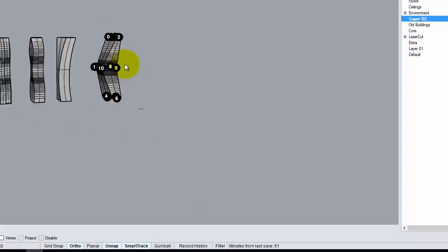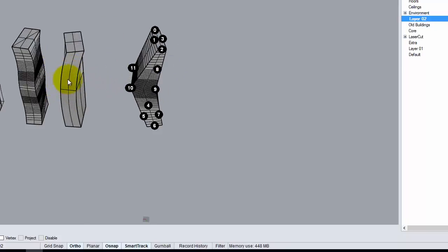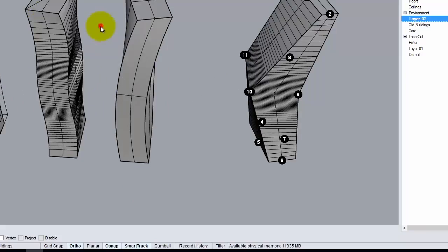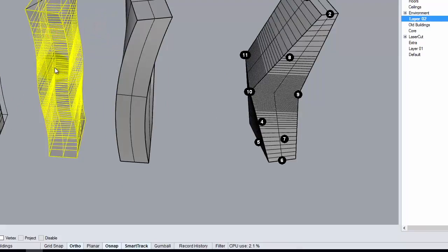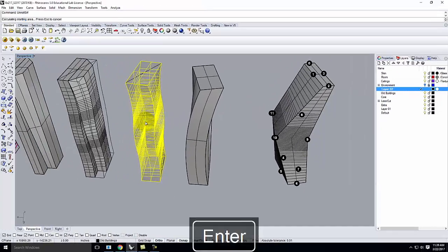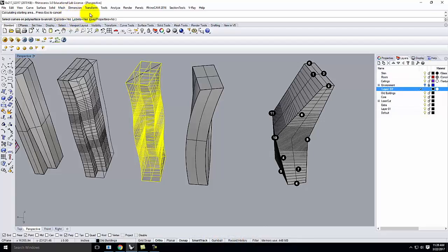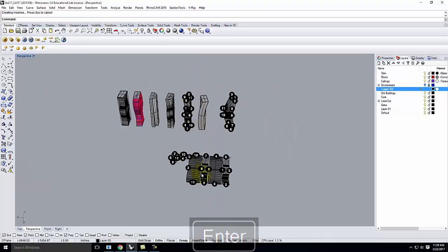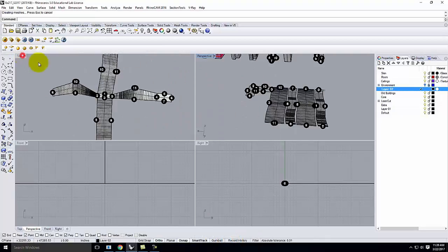So I can do the same thing with a curved surface. And I'm going to skip this one for right now. I'll do something slightly more complicated. I'll do this one. And this is, once again, a poly surface. Everything's joined. If I type unroll surface, select curves on poly surface to unroll, explode yes, labels yes, keep properties no. I'll go ahead and hit enter. I again get my labels, and I get my parts.